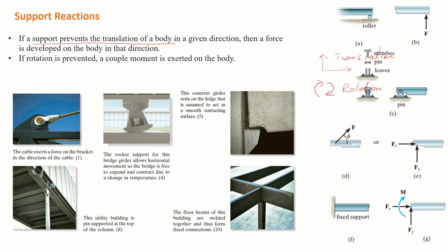So first we will examine, this is a roller support, and we can see that this roller can restrict its motion only in the y direction. So force in the y direction is shown here, and we can see this roller cannot restrict its motion in the x direction, and it also allows the rotation.